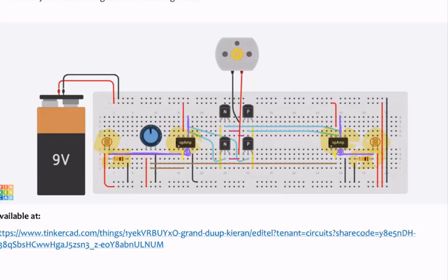If you notice, this inverting terminal is connected to the output of this potentiometer. So you have the potentiometer connected to pin number 2 of this op-amp, and also over here. You're going to set this potentiometer to a fixed value, which will generate some voltage, and that would be a reference voltage for you. The sensitivity of both LDRs can be adjusted by varying this potentiometer value. You can change the sensitivity if you like.